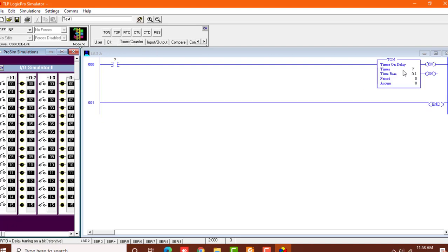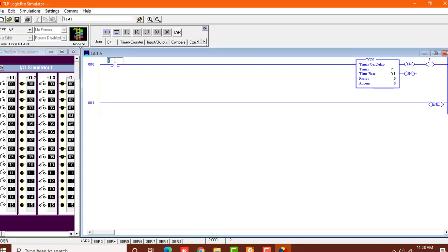I've pressed on T on and you can see that the timer on delay switch, the timer has appeared over here. Now what we need to do is I'll just place an output at the end. I've just clicked on the output and an output has appeared over here. Now I'll just rename these input switches with 1/0 and then this output switch as output 1/ sorry, we're going to name it with 2 because you can see that it starts with 2. So here it goes.